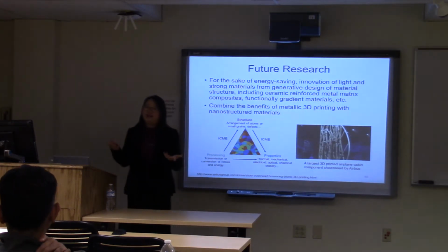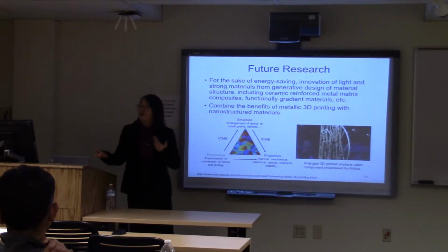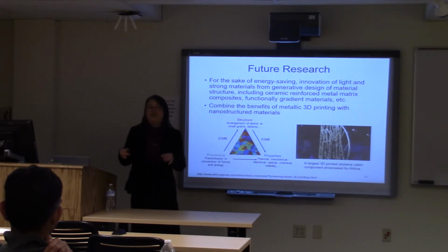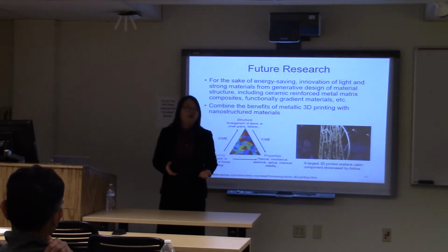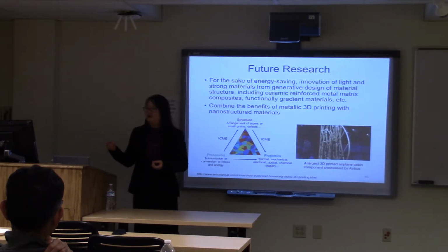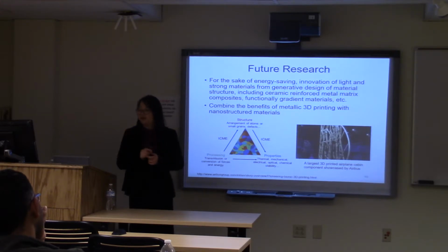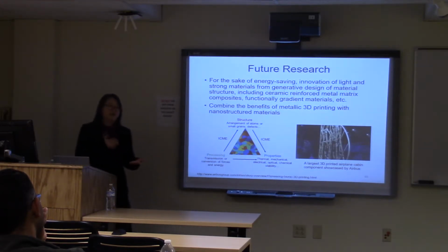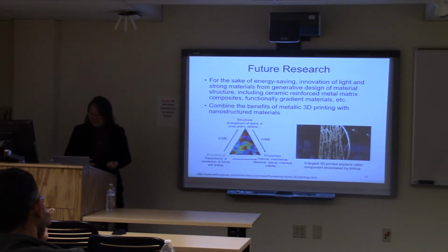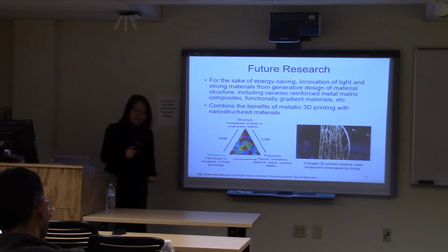Can we modify the process parameters, or instead of doing that melt and pour, can we do sintering instead? You're still using a laser or maybe sometimes an e-beam as a source to generate very quick, rapid sintering of your powders, so you can retain at least a part of the nanostructure in your parts, which still gives you higher strength and other properties here.